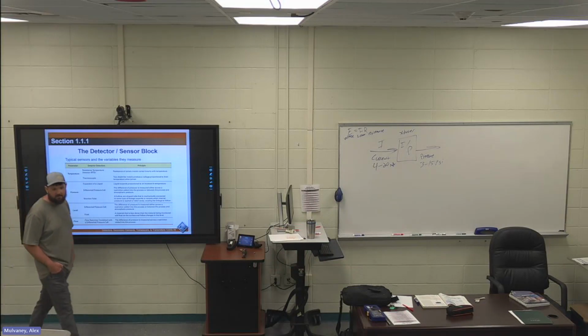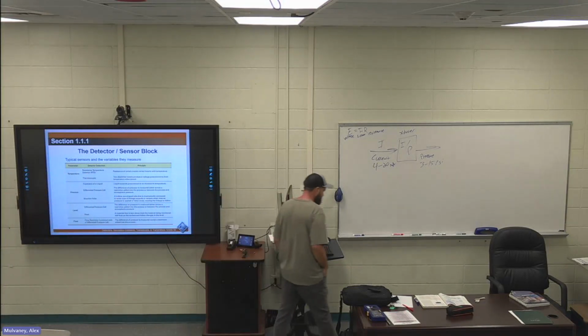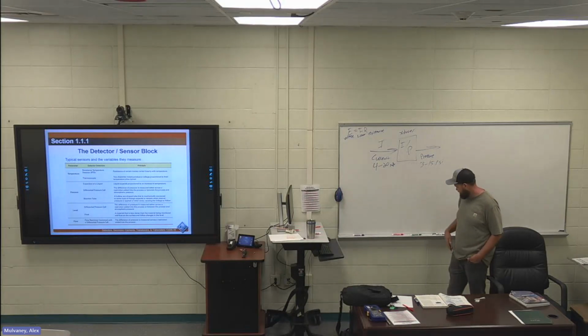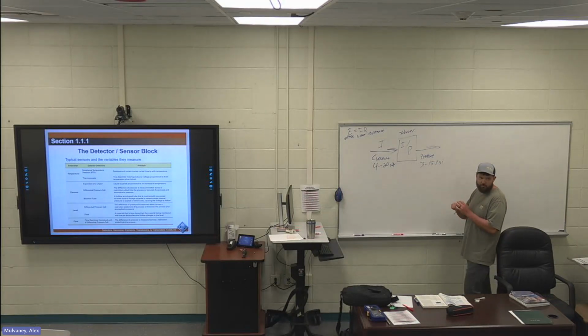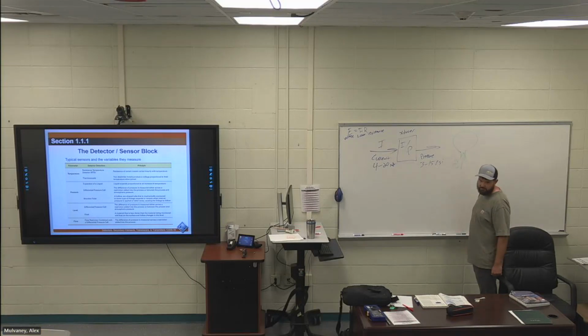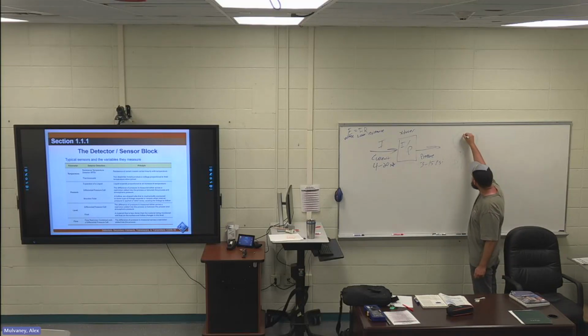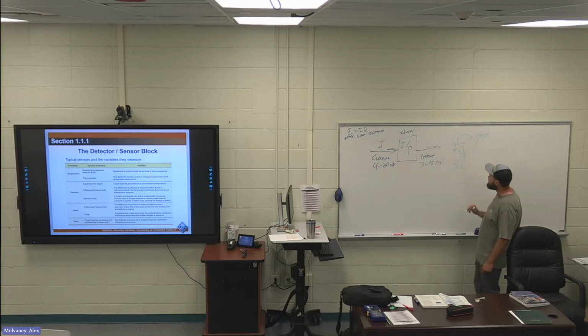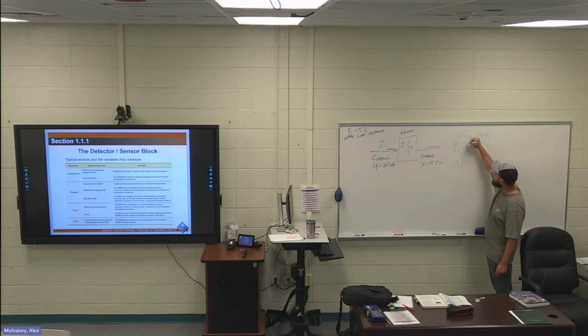What is it? Big picture. Where do you use them? Pressure gauges. So if you don't remember this, you can have a pressure gauge that looks like this, right? You got pressure coming in, right? The Bourdon tube looks something like this, and it's sealed off at the end here, and then the center of this is connected to a dial. So this is where you're like 0 to 100 psi, right? There's gears and stuff like that in here that make this turn at a certain rate.